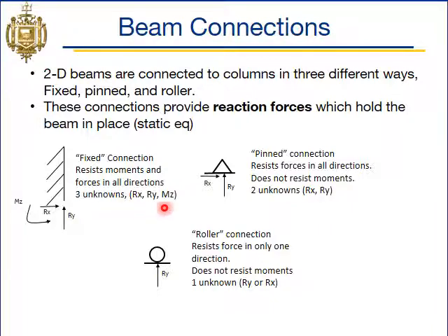And then this is probably the most difficult concept to understand in this lecture, the reaction moment. So that means we have this reaction moment here at our fixed connection, which means that it's not allowing for rotational acceleration of our beam. So just to do a quick sketch for you guys. If we had a beam here like this, right, that reaction moment is keeping this beam from falling and rotating like that. All right.